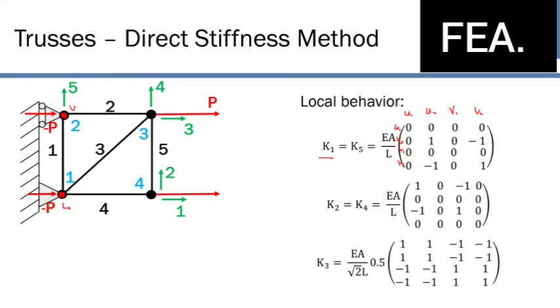Now looking at U based on two can move, right? So what we're going to have across here is that U can be affected by displacements in this other one, which can move in this direction, right? So in the Y direction, this roller is unrestricted. So as a result, this term right here, K21, essentially tells us that there's going to be a force in V1 due to U1. Sorry, I'm so sorry, guys. So this is actually V1. Sorry. So this is actually V1, this is U2, this is V2.